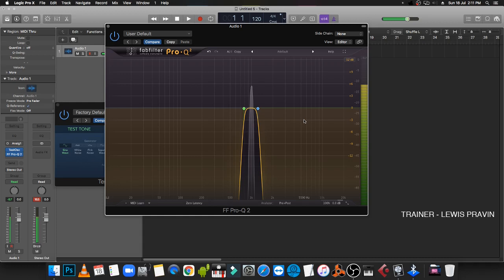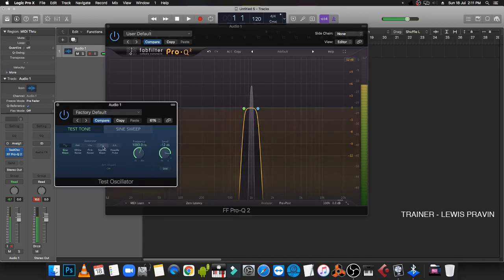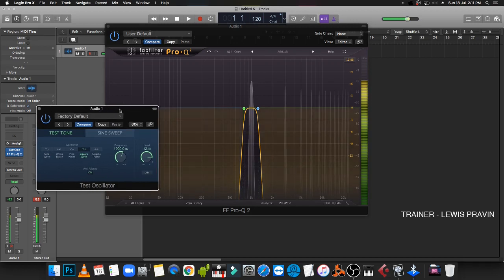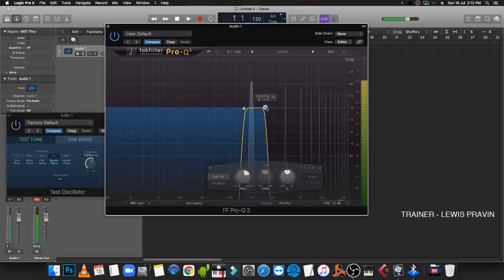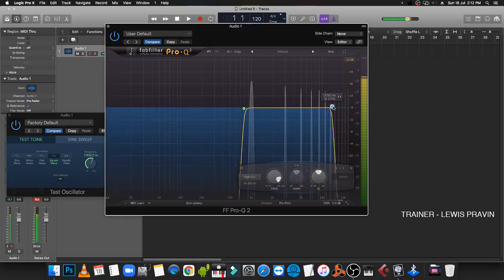Another thing I would do, for instance, is change this to a square wave. Now you will see the square wave has extra harmonic content, but I had filtered so much that these frequencies are now removed. I don't want that to happen. So as I see these frequencies popping up on the graph, I need to extend this far right so that I am still accommodating all other frequencies that are present within the range.